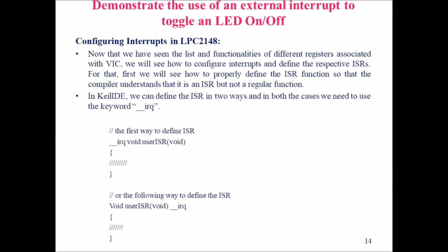The next concept is configuring the interrupts in the LPC2148. I will be explaining how the interrupts are configured in the LPC2148 microcontroller. As of now, we have seen the list and functionalities of the different registers associated with the vector interrupt controller, such as the vector interrupt address and the vector interrupt enable. All these things we have discussed, and basically these are associated with the VIC interrupt request.